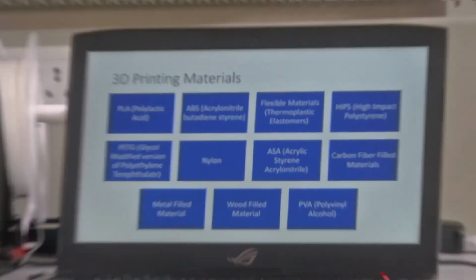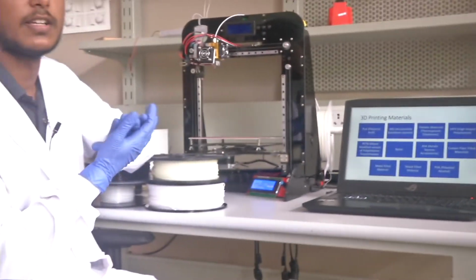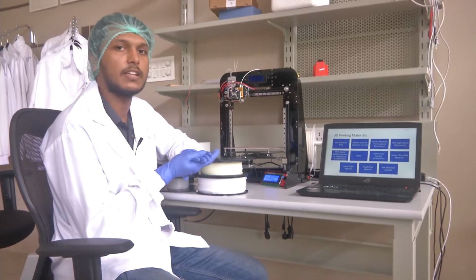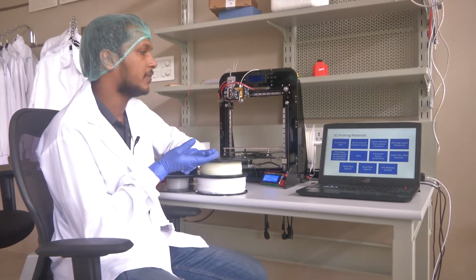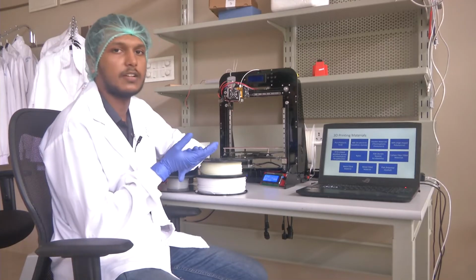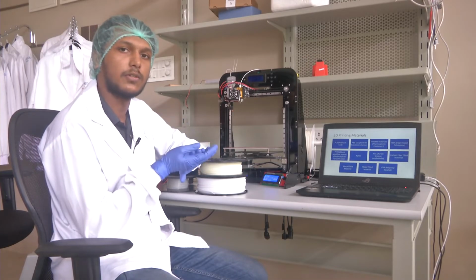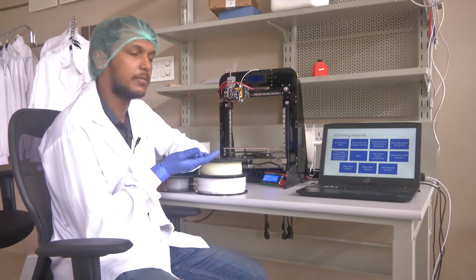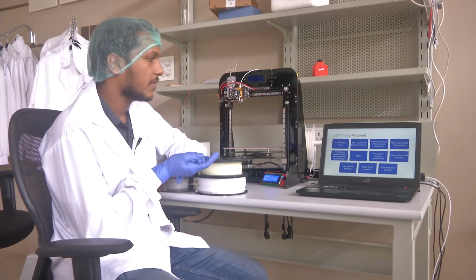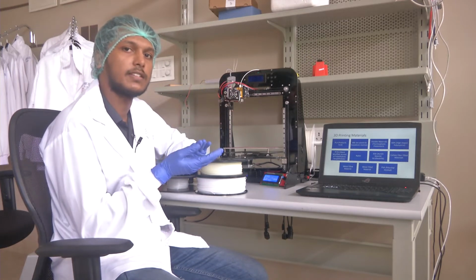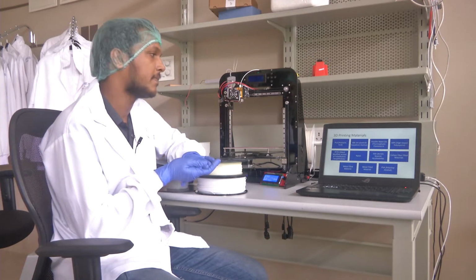If we are using the PLA material, there is no need of any heating in the printing platform, but ABS will shrink a little bit if it is cooled rapidly. So, that will need a heated 3D printing bed, and ABS is cost wise similar to PLA.